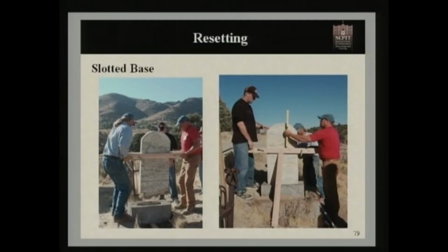Once we've put our lime mortar in, we've set our headstone in, the next thing that we really want to do is make sure we stabilize it. We want to make sure this stone doesn't move any while it's setting. If it does move, if it gets rocked while that mortar is trying to set, we break that initial bond that we've made there, and that's going to weaken that joint later. So we want to make sure to clamp this up to support it while it dries, and this could take a day or two.